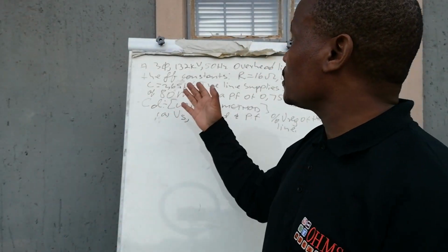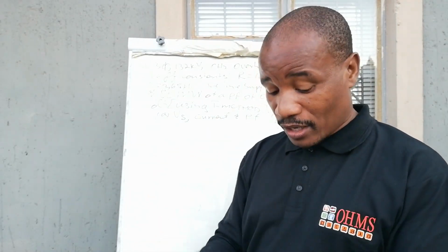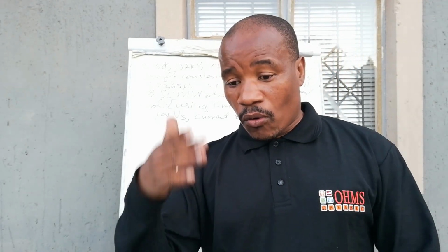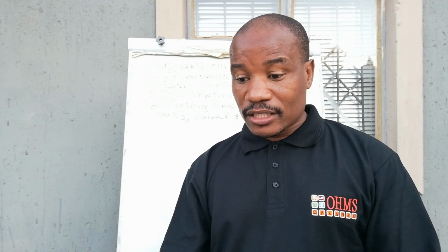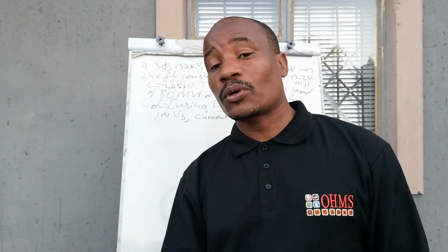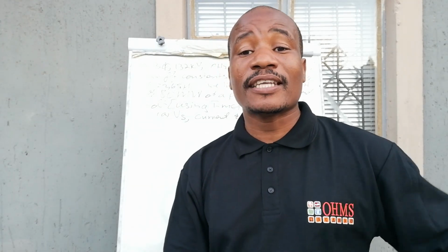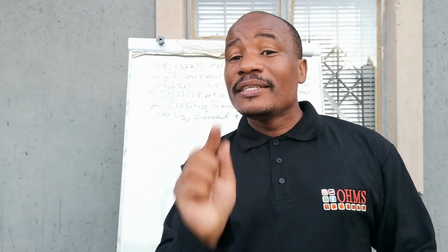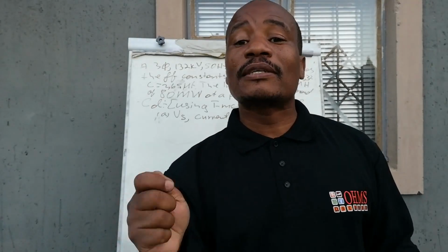We are yet to discuss the type of conductors. Maybe you heard from the first video on transmission lines that you have to compare copper and aluminium and come to a decision as to which one you should use. Even the aluminium itself has its own shortcomings. That is why sometimes you may find it has to be reinforced in order for it to be more flexible in transit. Remember, aluminium is only 60% conductive.